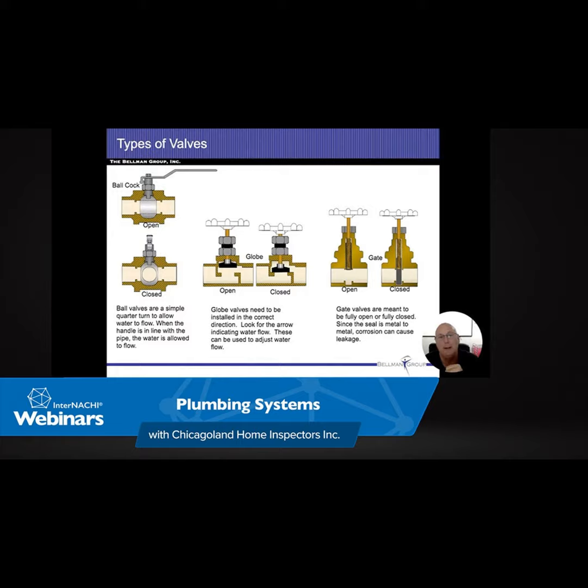The vast majority of plumbers are going to put them in what we call parallel, and that's what we're looking at right now. So basically the cold water comes in and it splits off, goes to both water heaters, and then the same thing with the hot water when it comes back. They both come together, and then that feeds the hot water to the house. Theoretically, as long as they're equal, water's going to flow down the same line, plain and simple, all right?